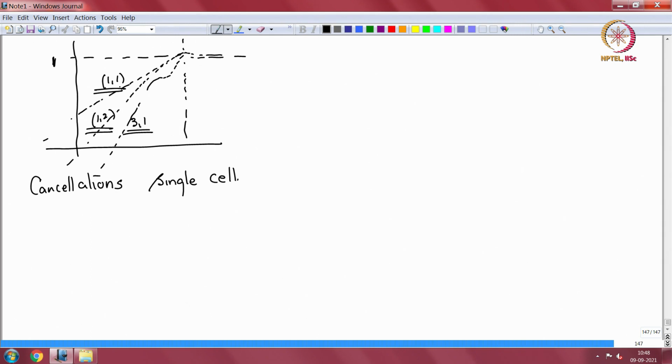So you can see that the 1,1 mode will have the biggest quarters at the 4 corners. So it starts off higher and cancellations within it are less, so it has the highest radiation efficiency or radiation resistance. Whereas all other modes with a higher number of half circle patterns at low frequencies, the area of a single panel is much smaller, and therefore they radiate less sound, and so they start off from a lower value.